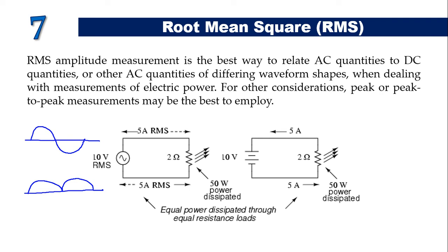Unfortunately, a measurement based on work performed by a waveform is not the same as the waveform's average value, because the power dissipated by our load is not directly proportional to the magnitude of either the voltage or the current. Rather, power is proportional to the square of the voltage or current applied to the resistance.